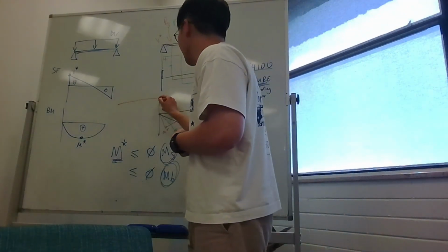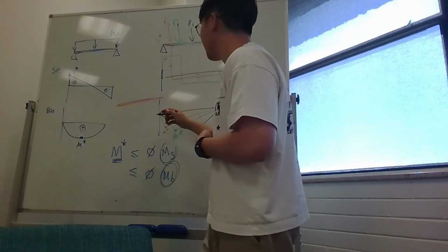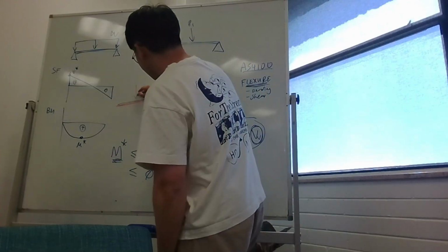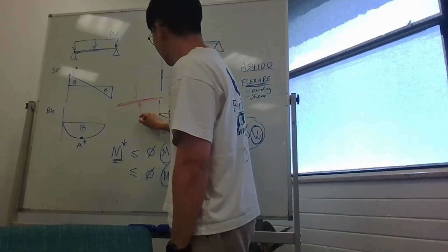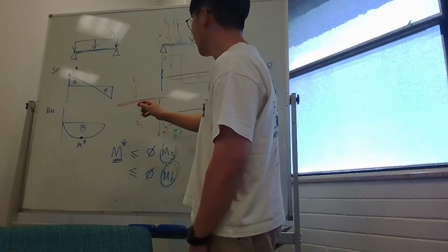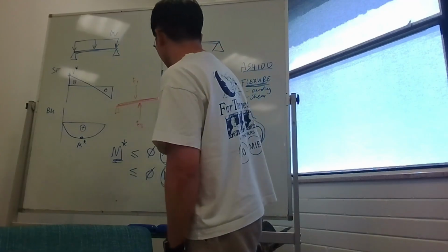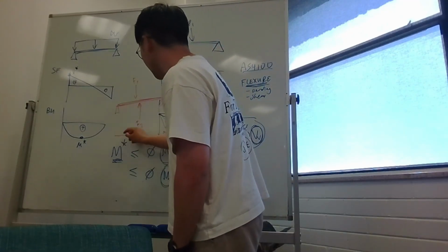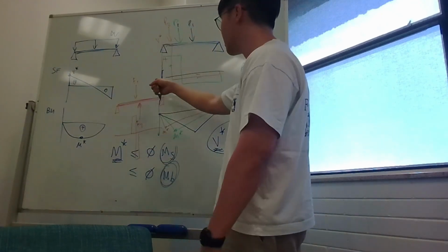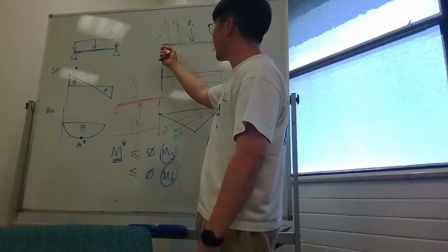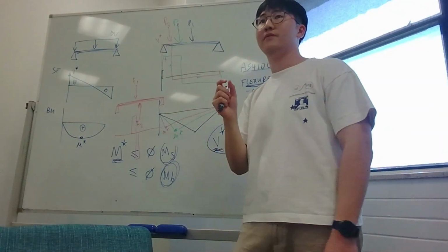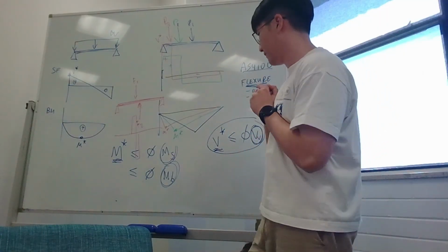If I had a piece of paper, we're looking at a piece of paper sideways, right? And I have the blades of your scissors, in and out of the page. That's the force due to one side of the scissor, and that's the force due to the other side of the scissor, right? So the shear force diagram of this would look like that, let's just say with support on both sides. So when you have 2 point loads that are very close to each other, including reactions from your support, you get a very, very high shear, okay? And that induces shear failure, okay?